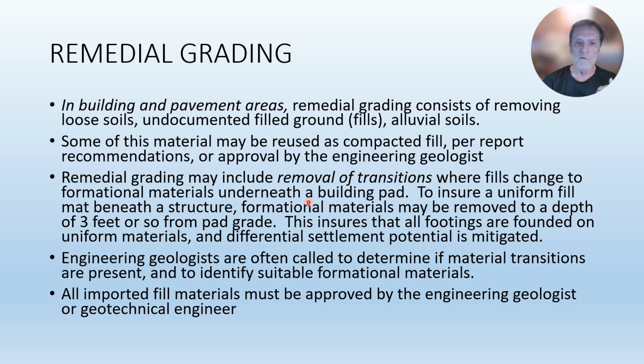This paragraph is important. So in that scenario I discussed where you cut the high side of a hill and fill the low side, you may have cut down the formation on the high side, and so the rear of the building pad next to that cut slope may have formational material on the surface.